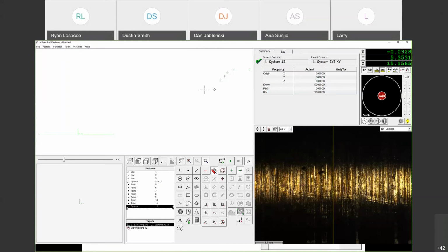One way to think about it is that if you're looking at the front of the machine, you can see the Z direction and you can see the X direction, but the Y direction is going away from you. And whatever's going away from you is not included in this right here. So if I click my PCS view, this helps me out seeing what the software is looking at the points that I took.